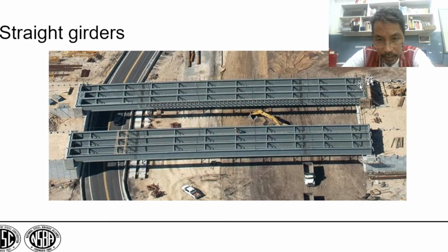It clearly shows the girders here. Okay, and because of the shadow, I can surmise that these are the diaphragms. The diaphragm is a cross frame type diaphragm here. So these are the diaphragms: end diaphragm, interior diaphragm 1, 2, 3, 4, 5, 6, 7. There must be a diaphragm here. Currently there is none, because it is still being constructed. Similarly on the other side, corresponding diaphragms are there.